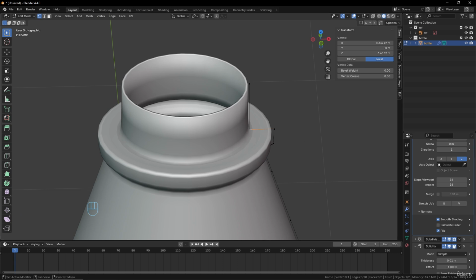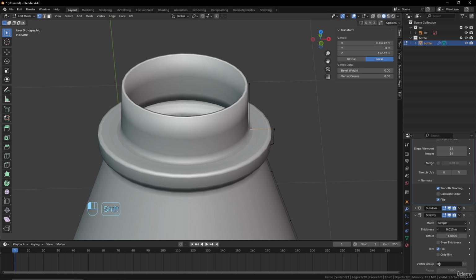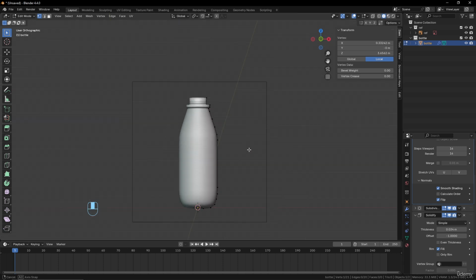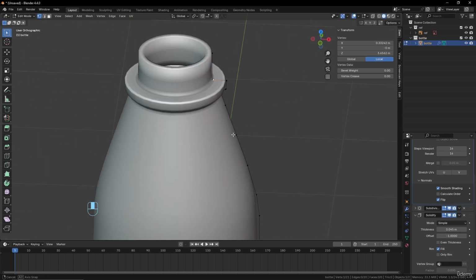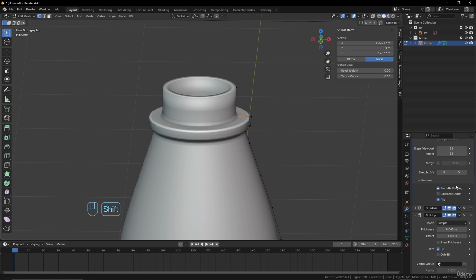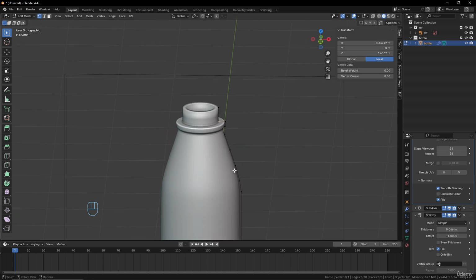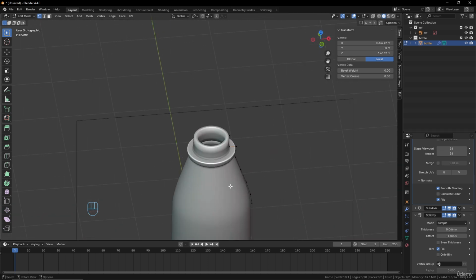We can adjust this value a little to make it thicker. Okay. And we will have something nice now. That looks very nice actually. Okay, not too much on this value, because if you add too much thickness, it will go inside and go outside here because we have a thin part here. So let's add until there. It will be perfect. Good. Now we have a nice bottle.